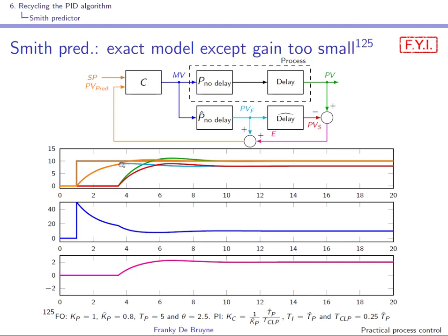And since this predicted PV is going to increase, right, but the controller is reacting by slowing down the system. And as we had anticipated, well, both the predicted PV and the actual PV are going to go to set point, and we have a zero steady state error.